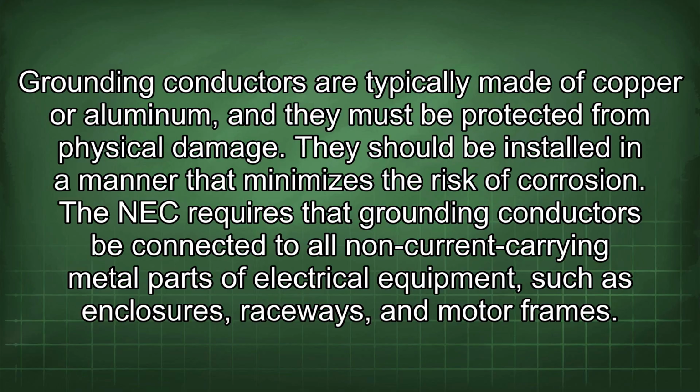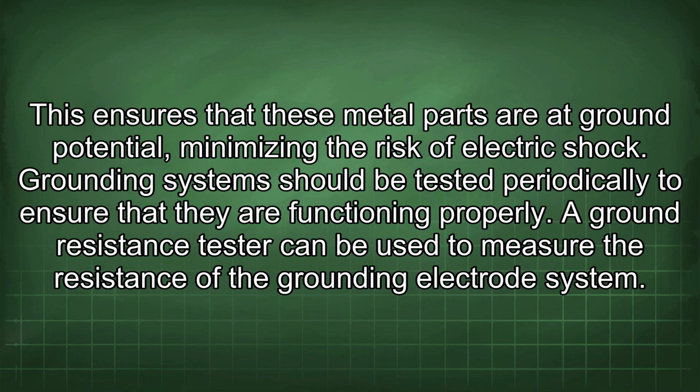The NEC requires that grounding conductors be connected to all non-current carrying metal parts of electrical equipment such as enclosures, raceways, and motor frames. This ensures that these metal parts are at ground potential, minimizing the risk of electric shock.